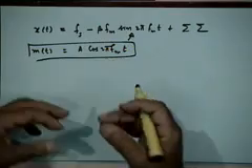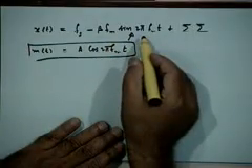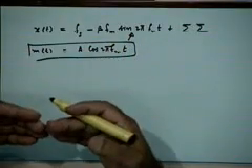So in a way, when you do PPM, in fact, if you remember, somebody said that you can differentiate a PWM signal and come close to a PPM signal. You can see that from the spectrum expansion also, and therefore that also gives you a clue to how to demodulate. Now can you give a clue? For demodulating, you first pass it through a low pass filter and then integrate.